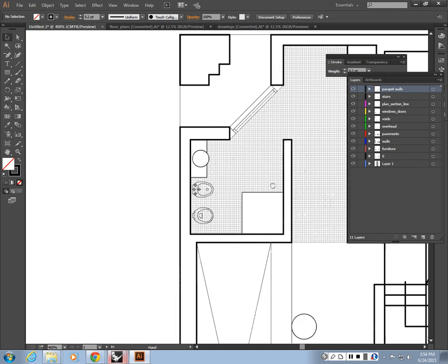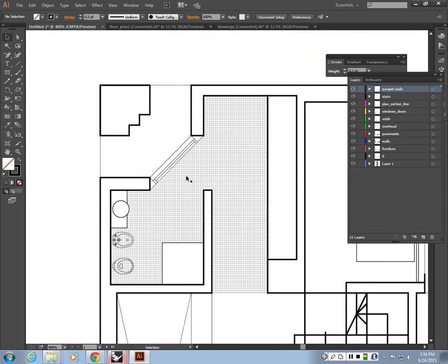So the relationship is something like this, basically, if you zoom in. The structural elements, the cut walls should be thicker, or the thickest elements on your drawings. The hatches, the floor tiles, they should be thinnest, because they're going to be really dense elements. Then the next cut elements are walls and doors, and they should be the second thickest, right? So the walls are the first, second thickest are windows and doors. And then the third one is furniture, basically, right?